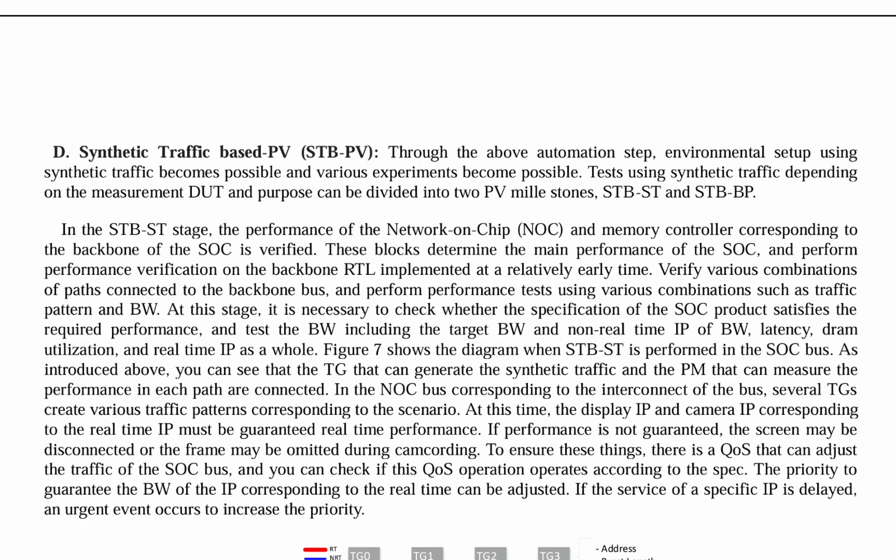At this stage, it is necessary to check whether the specification of a SOC product satisfies the required performance. The test covers the bandwidth, including the target bandwidth and the non-real-time IP bandwidth, latency, and DRAM utilization and real-time IP as a whole.